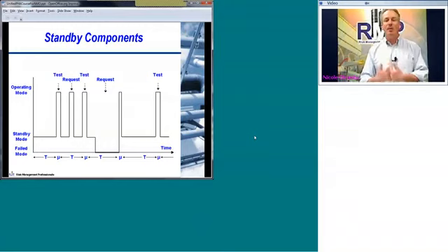You may have to use various test modes, and then it could fail in the standby state and you not know it, and that's what this chart is representing: all these different states and the fact that it can be failed and you're not knowing it. Now, one of the nice things about modern electronics is that there are a lot of smart sensors and fault-tolerant devices out there that can really help you identify if something's happened with the equipment, especially electronics. Those have been really helpful for lowering the incidence of undetected failures and making sure that you maintain overall availability, minimizing overall unavailability of key safety equipment.